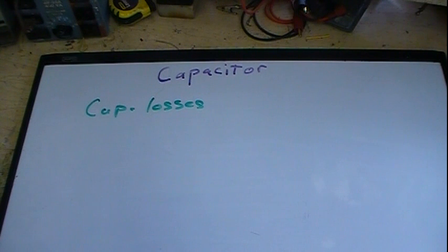It's not even practical to try to measure it unless they start breaking down. If the dielectric starts to break down, then the leakage will increase, and that's why we have things like the ICL 950B or the various capacitor testers. But for all practical purposes, leakage is not a big issue. It's a little more of an issue in electrolytics, and in the old days we considered that power factor. Today, ESR,